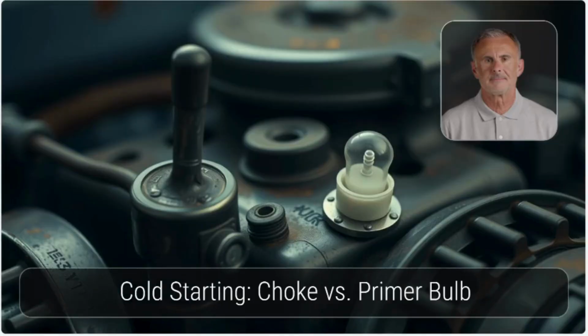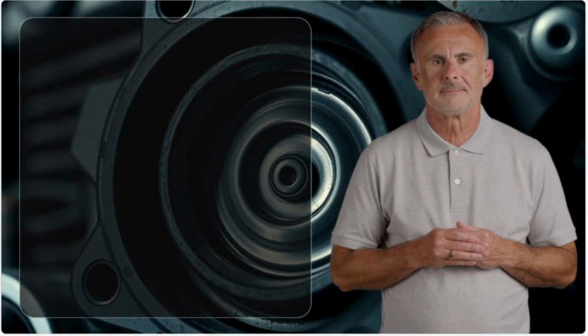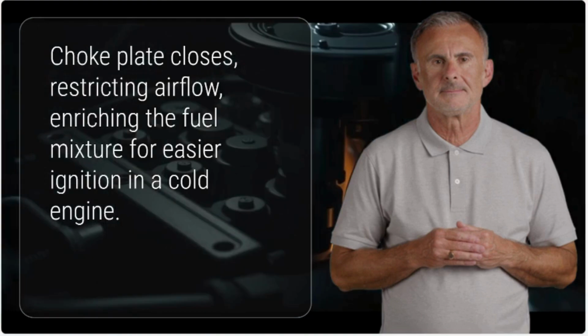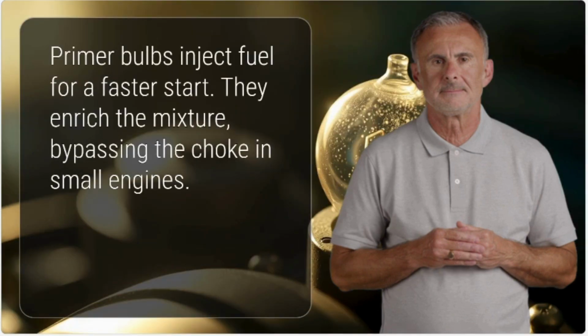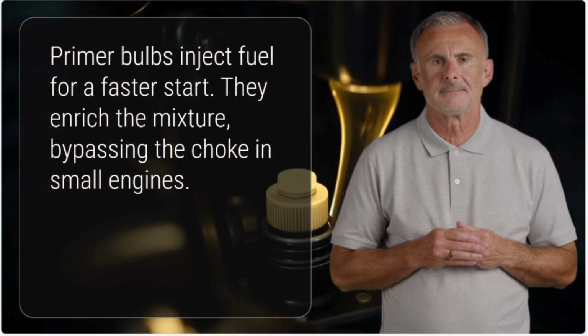Cold starting: choke versus primer bulb. To assist with cold starting, carburetors may use one of two enrichment methods. Choke plate: closes partially to restrict airflow, thereby increasing the proportion of fuel in the mixture. This richer mixture is easier to ignite in a cold engine. Primer bulb: found on some small engines, this manually operated bulb injects fuel directly into the intake path, enriching the mixture for a faster start without using a choke.